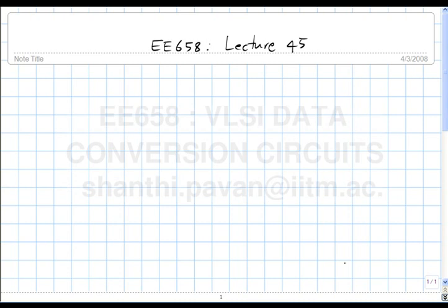One problem that we recognized with respect to the discrete time modulator was that since you're sampling before you get into the ADC, you need an anti-alias filter. Perhaps since you're sampling in this continuous time delta sigma modulator at the output of the loop filter, the aliasing function becomes easier. It could be tougher also, but let's take a look. And before I get there, I want to clarify a couple of points.